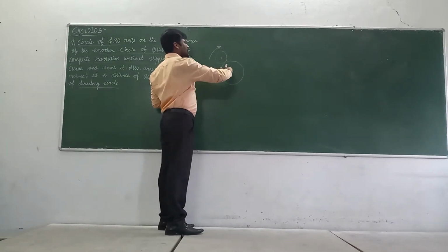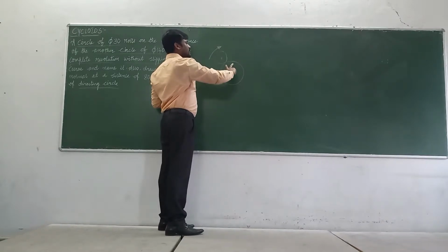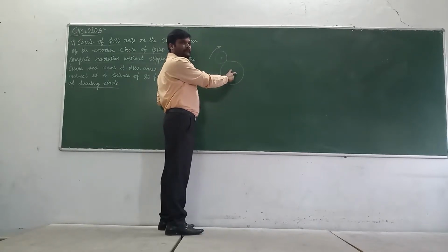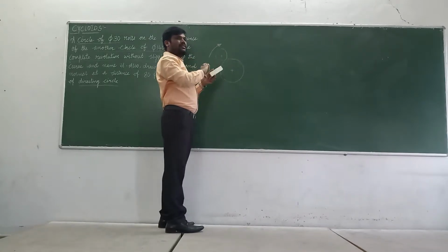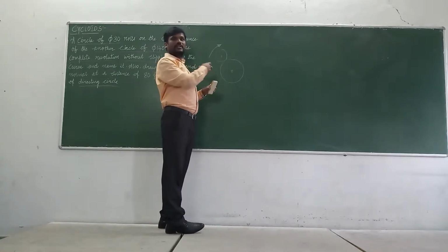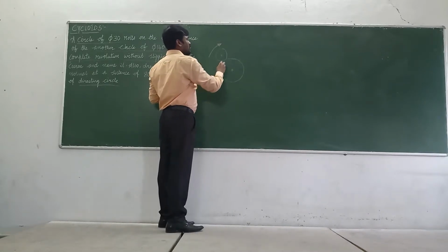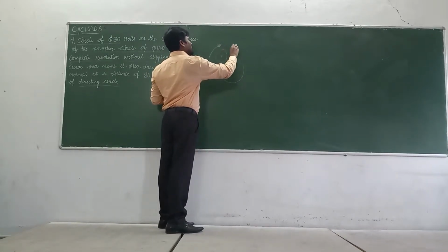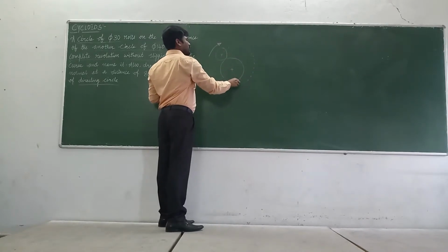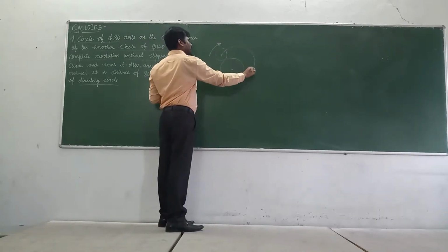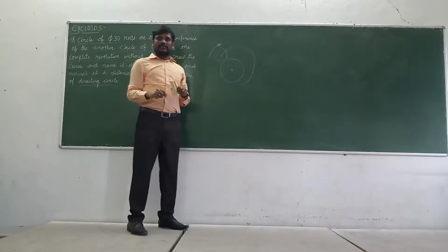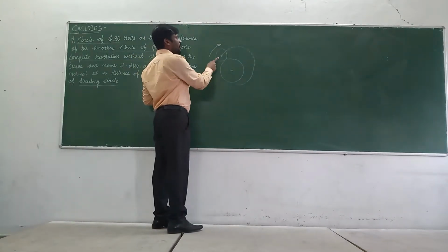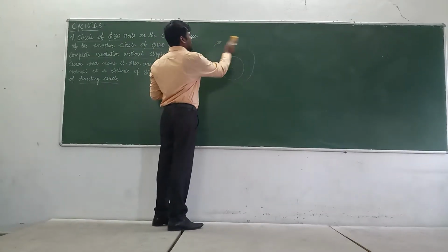So what the question asks here is that the 40 diameter circle is going to roll upon the circumference of the 140 diameter circle. This is nothing but the application of gear teeth meshing, one gear's teeth meshing with the other gear, an application concept for mechanical engineers. I am going to trace the curve like this, and I get a cycloidal curve of cyclic nature. When this circle moves on the circumference of another circle, it is termed an epicycloid.